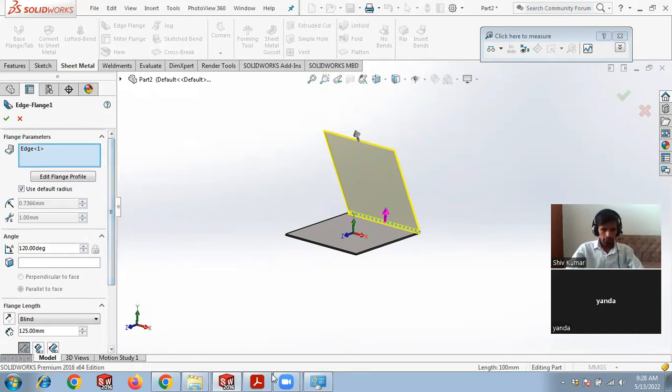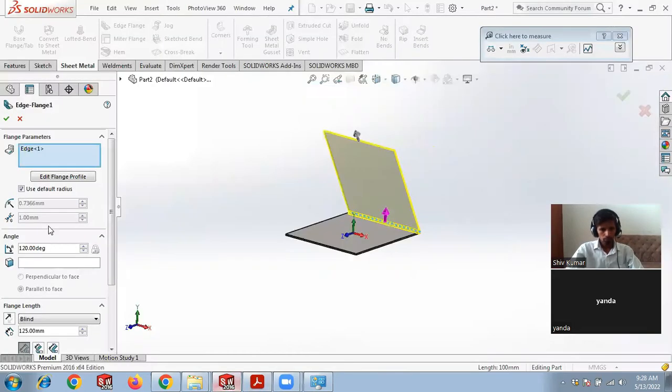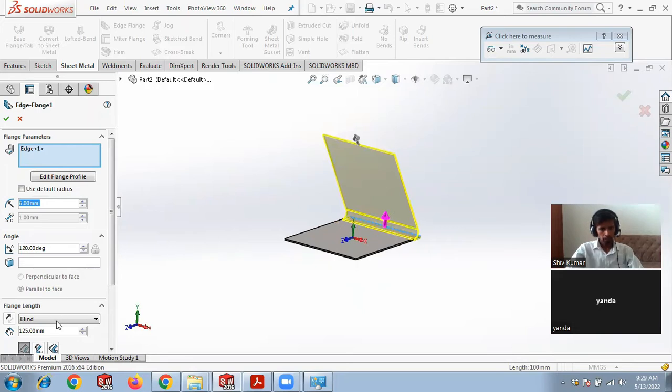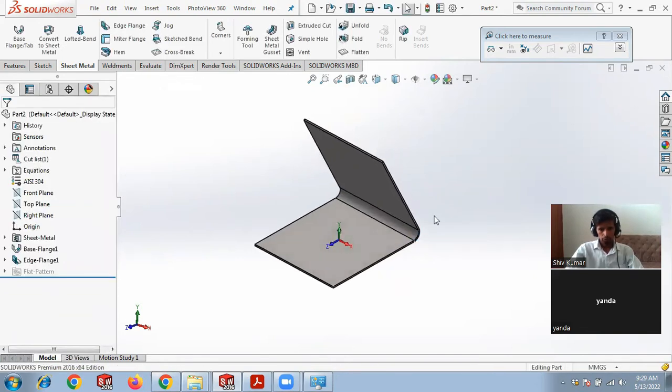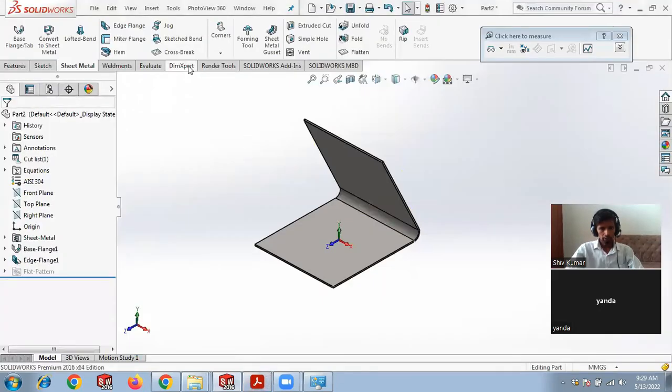And for radius, because you can see here, a larger radius has been used for visual purpose. So I'm suppressing the default radius and using 10 mm radius, or maybe 6 mm radius. Okay, and the height we have already defined as 5 inches, approximately 125. Okay, I'm doing that. And now we have again a band on this side.